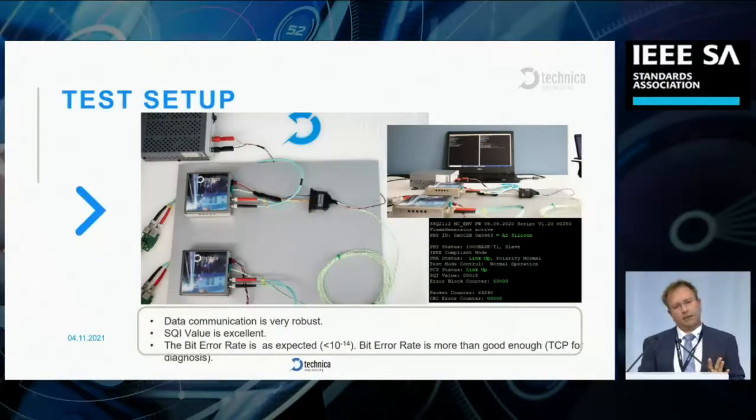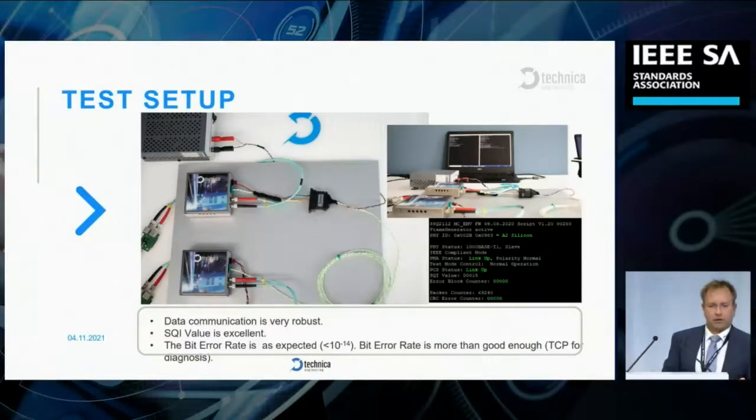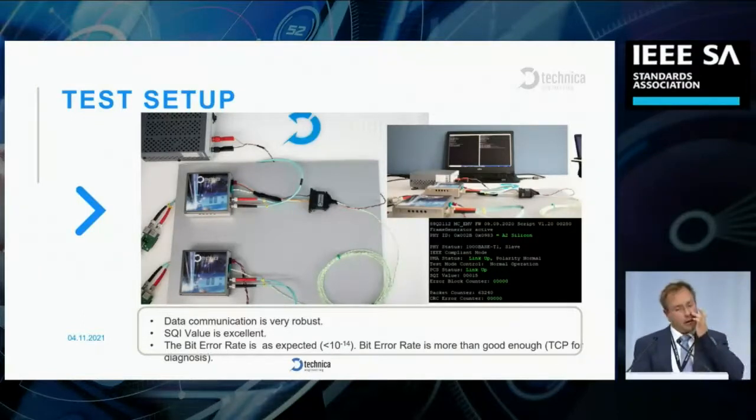Inside our media converters, we have traffic generators that generate 1 gigabit traffic, full duplex, in both directions. There is a monitoring tool that can be connected optically to do some EMC tests, of course, but you can see it directly on your desk. You can see the data throughput, the packets, and even whether there is any CRC error.